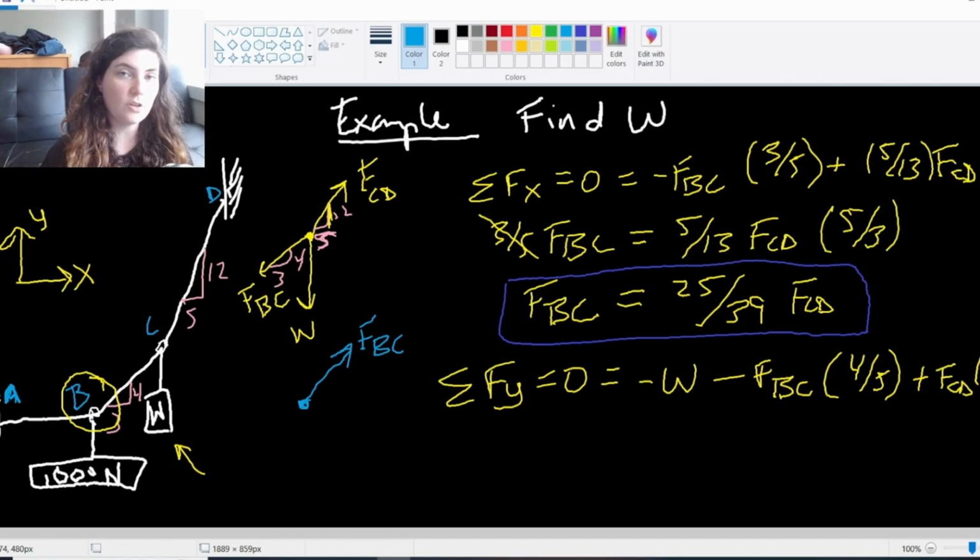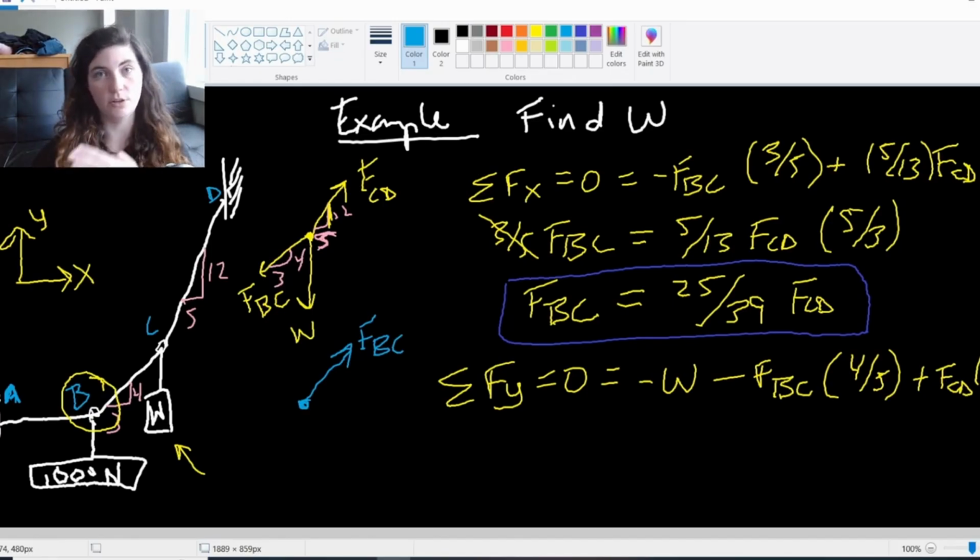Now remember, the forces always go in the opposite directions, right? So from this point C, FBC was going out, down in the negative x and negative y, and now you're seeing the equal and opposite. You're seeing the same force now in the completely opposite direction coming through the cable. This is standard. This is how we always denote this, which we'll talk more about later, but right now it's important to understand the concept that we're always pointing these forces away from the point we're looking at.